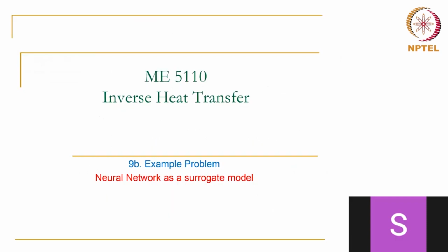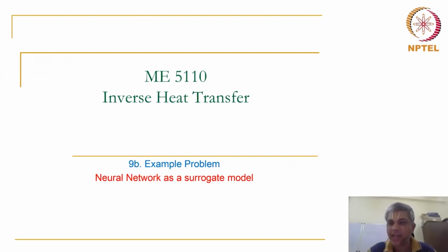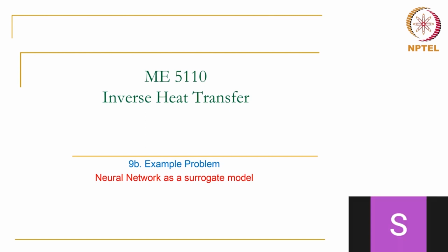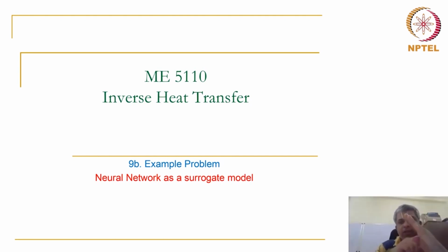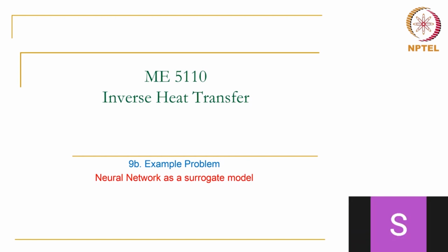So the flux from the left wall should be a negative value. Just check the sign. I might have made a mistake. Flux from the left wall. No, on the right wall will be negative. Flux from the left wall should not be negative. Why should it be negative? Internally the slab is generating heat. So on the left, you look at the slope. The temperature is going like this. Correct? The heat is being added on the left. That's why it's going up immediately on the left wall.